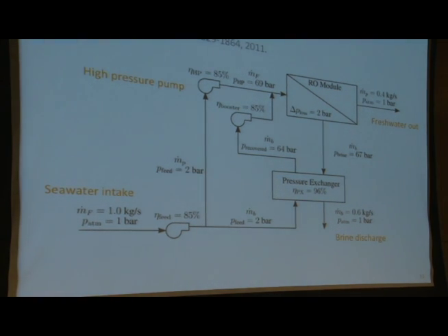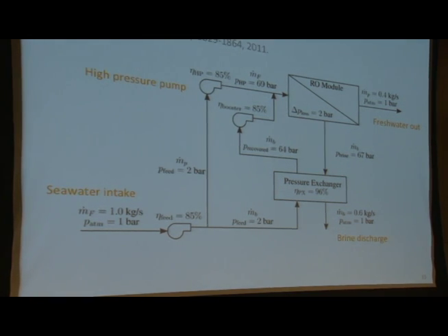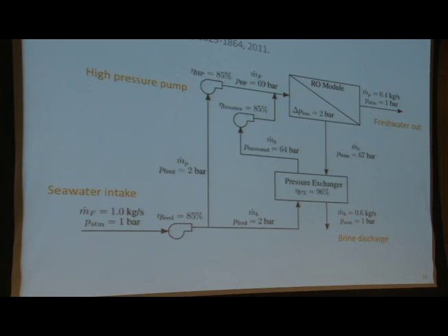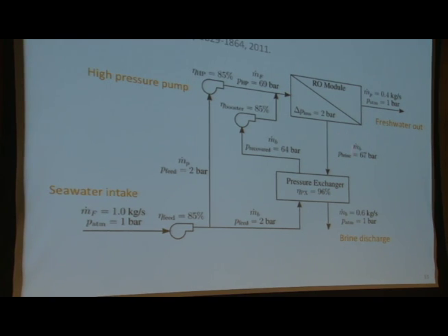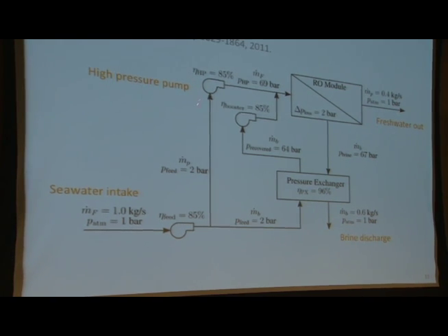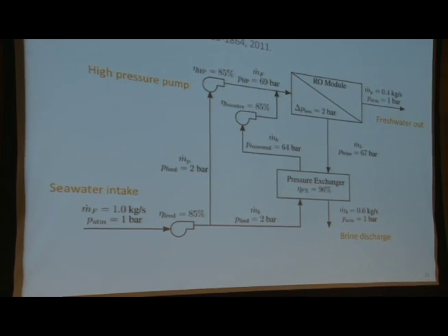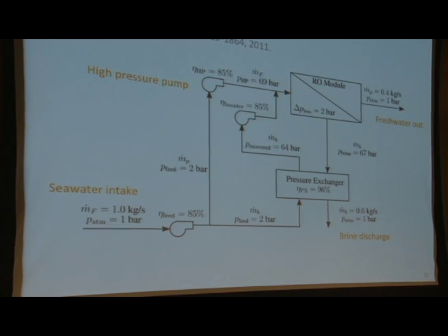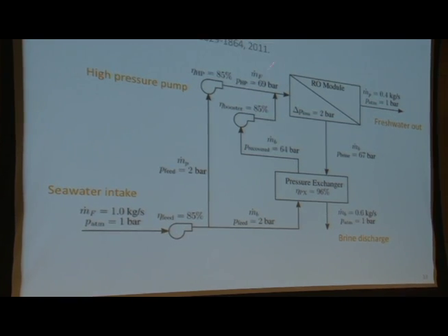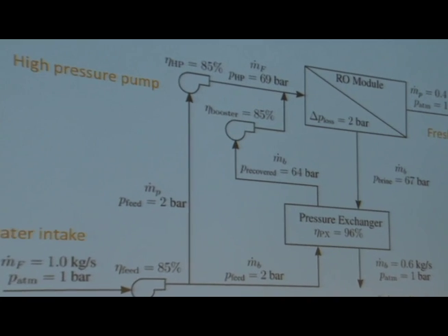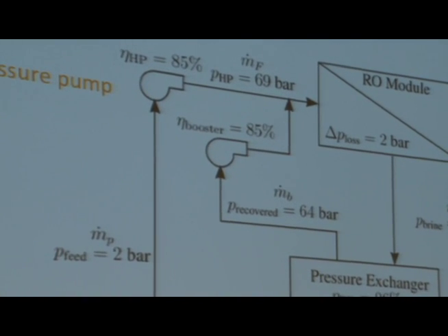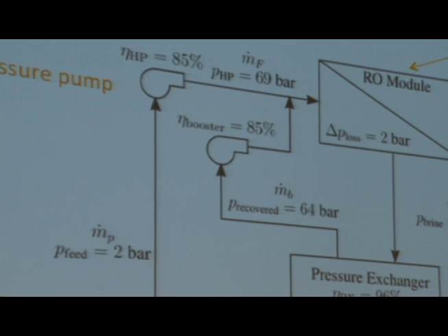And that energy is recovered through something, you can think of it as a turbocharger pump. The actual devices, the pressure exchangers, are rotary machines. They're really very clever engineering. And they're very efficient at transferring this pressure to some of the feed. The rest of the feed is taken through a high pressure pump and brought in here. So you can ask, what is the biggest source of loss in here? The pumps are actually pretty efficient. In fact, for the largest plant, this high pressure pump has an efficiency in the range of 89%. These are really efficient pumps for reasons that are clear.